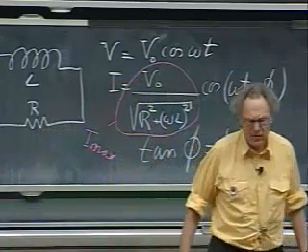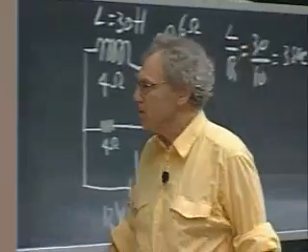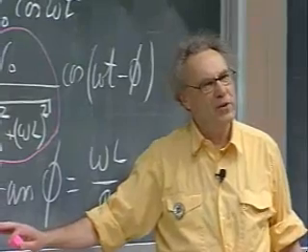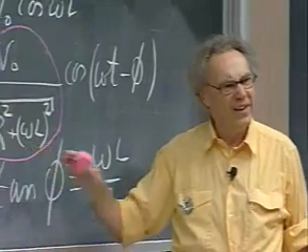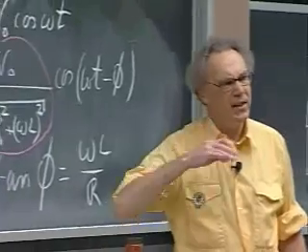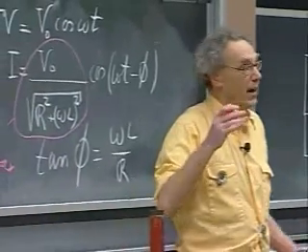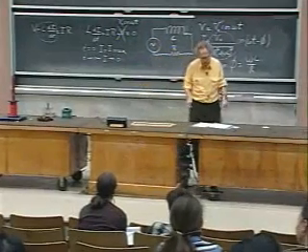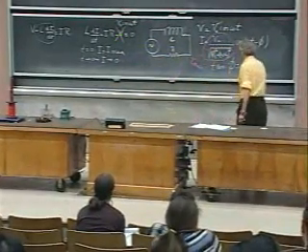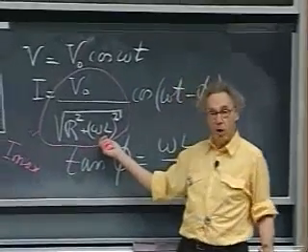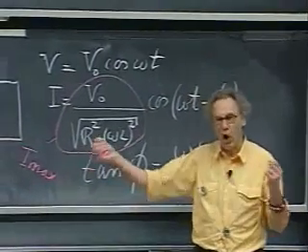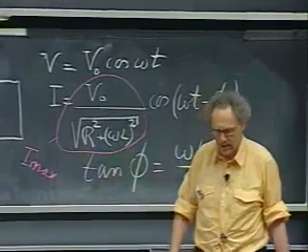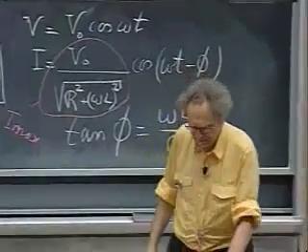And if omega is very high, then the resistance here becomes very high, and so your current becomes very low. Well, that's intuitively pleasing, because if omega is high, then the changes, the dI/dt's, are very, very high. And therefore, if there are very fast changes, the induced EMF is going to be high, and so the current will be low. Also, if L is very high, then the system also is capable of fighting back very hard. And so it puts up a large resistance. So it's also pleasing that you see the L there downstairs.